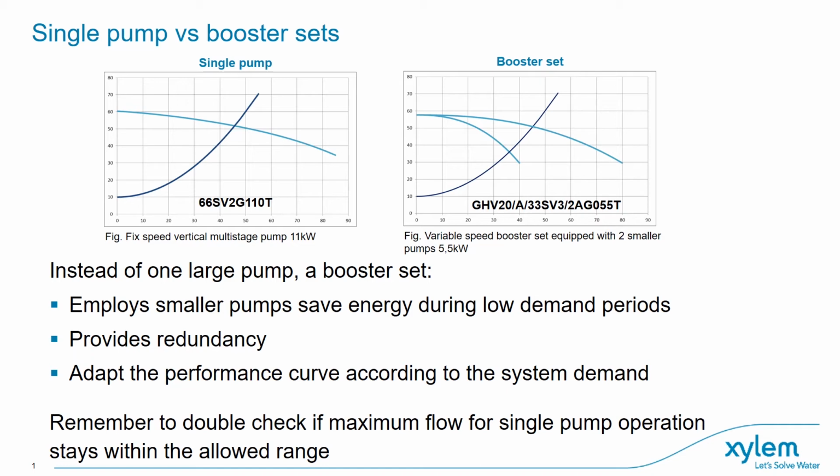And generally what you tend to find is even when both pumps are running, they're generally not running at full speed. You'll probably have one running at full speed, one running at 70% of its load. So there is still an energy saving to be had with a 2-pump variable speed system, even if they're running at very close to peak flow.